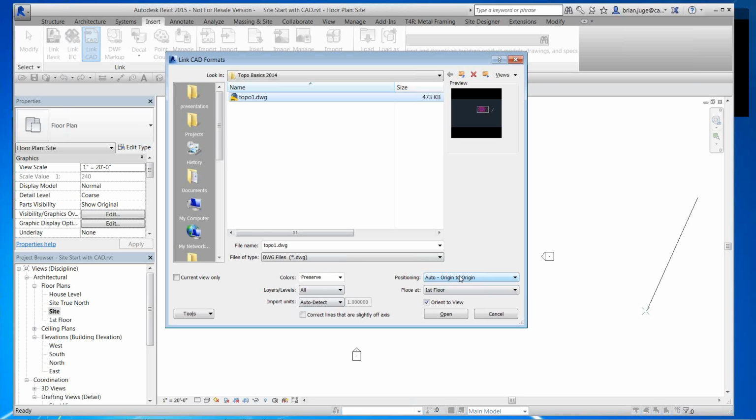So important things to point out when you're going in and you're getting the topography in there. If you're working with the civil engineer, we have state plane systems and state plane coordinates and all this stuff that picks up on the origin. A lot of stuff that the civil engineers care about, but us as architects, we could, whatever. The only problem with that is that inside Revit, we have something called an origin point. So when we're linking this origin to origin, those origin points cannot be outside a 20-mile radius. Okay, so we have to stick within that 20-mile radius.